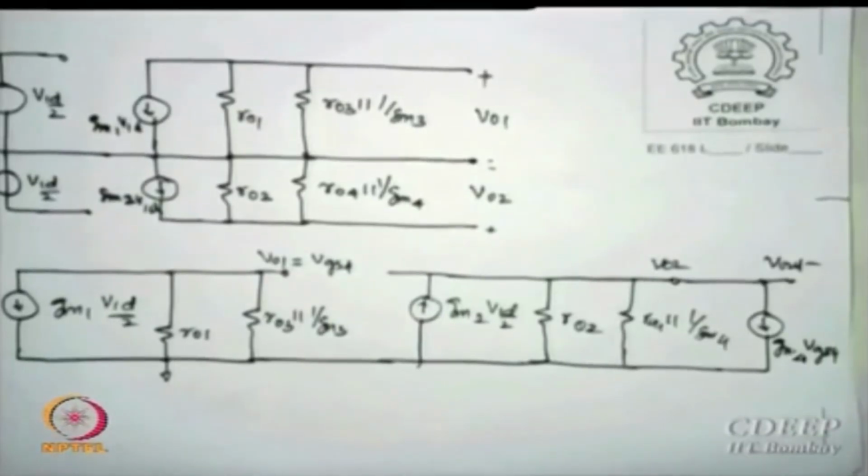Transistor M4 is also receiving AC input, and at M2 you are actually putting an AC input. Both contribute to the output of the second stage. They must be superposed. The problem was that because VGS is for a p channel device and the other is an n channel device, the direction is opposite, so one of them has a minus sign, so probably they may still add physically in numbers.